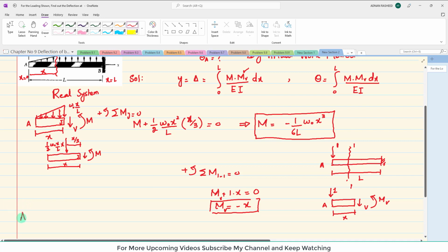Let this beam be AB, and the boundaries are that x starts from 0, x is greater than or equal to 0 and less than or equal to L. We have the actual moment, which is minus 1 over 6L W naught x cubed, and the virtual moment, which is minus x.